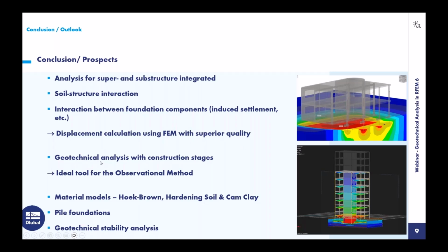Another hint is that the geotechnical analysis combined with construction stages can be an ideal tool for comparing your expected behavior with measurements at the site. If you have a project that is sensitive according to settlements, it can be quite useful to compare it with the calculation and check whether the settlements are as expected or not, and you should have a look at it more in detail. This just as a short summary.